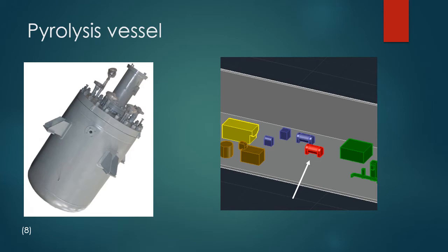This system is using slow pyrolysis, sometimes called torrefaction, which occurs at a slightly lower temperature over a longer period of time. This results in maximizing the product of biochar and minimizing the other products of bio-oil and syngas. The biochar is sent to the biochar storage to be mixed and made into the potting soil. The bio-oil is sold in the commodities market as a revenue stream.